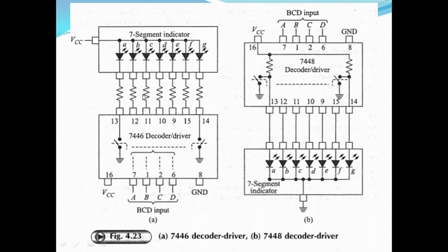This is called the 7446 decoder. It is decoding the BCD inputs and then driving the 7-segment indicator. That's why it is known as a decoder-driver.